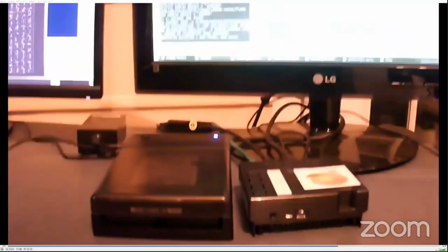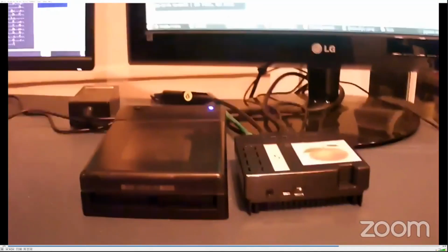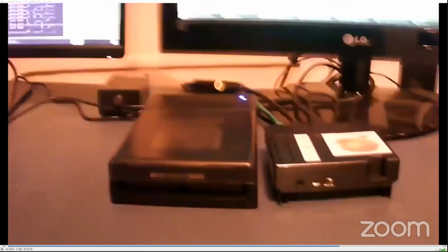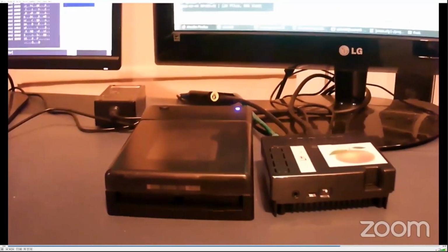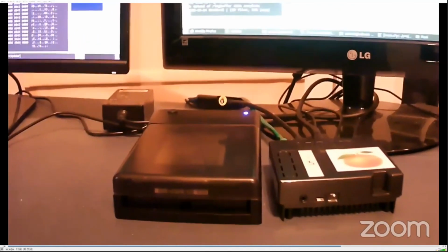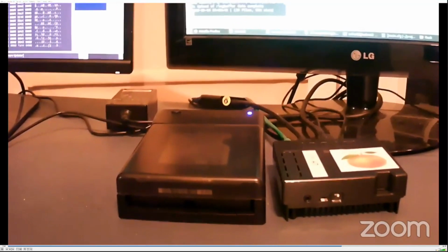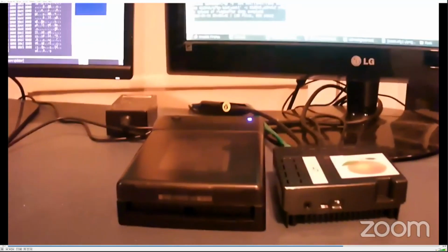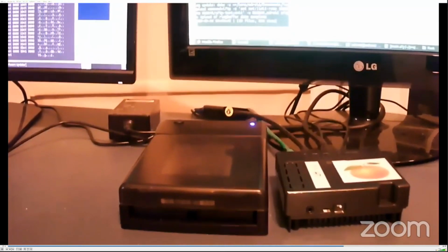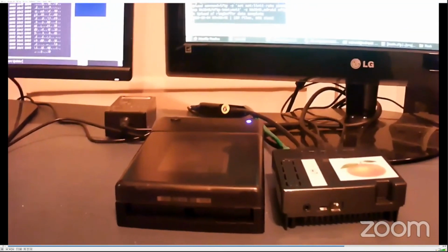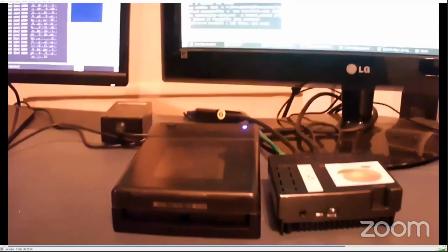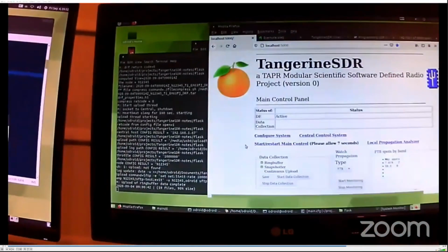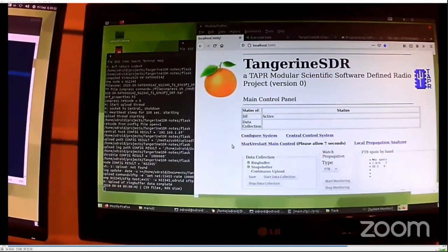This consists of an Odroid N2 and a Western Digital Purple series hard drive. The purpose of that is to use a video surveillance type of disk drive so it can survive the large number of reads and writes necessary to do the ring buffer function. The system over here, there's a couple of controls.